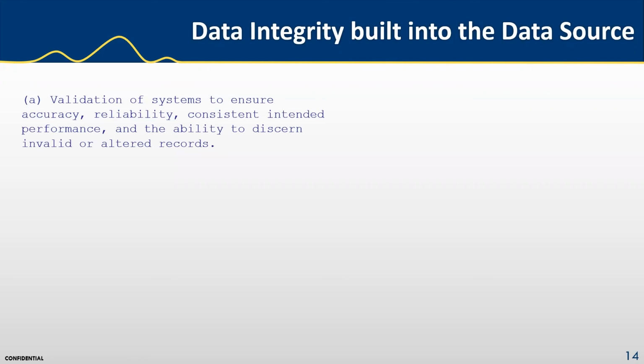So we can clearly see that the additional sources of data validation do in fact help secure the data's integrity. Another huge advantage is that with an early warning detection built in, with what we have just seen in that video, it can assist in ensuring calibrations are intact. What I mean by that is, based on observations from our service departments around the world, the number one failed calibrations root cause is sensor contamination, and mainly from cleaning solutions.